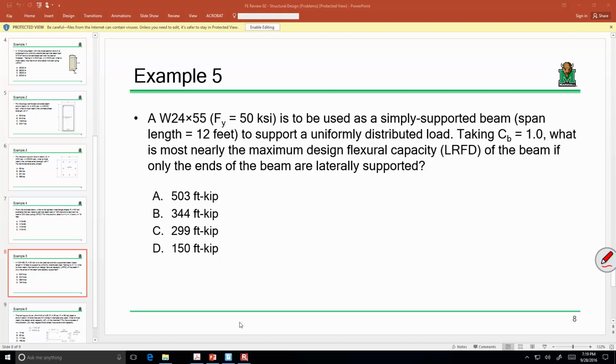It wants to buckle. A portion of the beam in tension does not. There's an internal conflict going on within the beam, and the beam ultimately sort of kicks out and twists. And it experiences a phenomenon known as lateral torsional buckling. Have you ever heard that term before if you haven't had steel? Okay. All right, so that's a very familiar failure mode for a steel beam, okay?